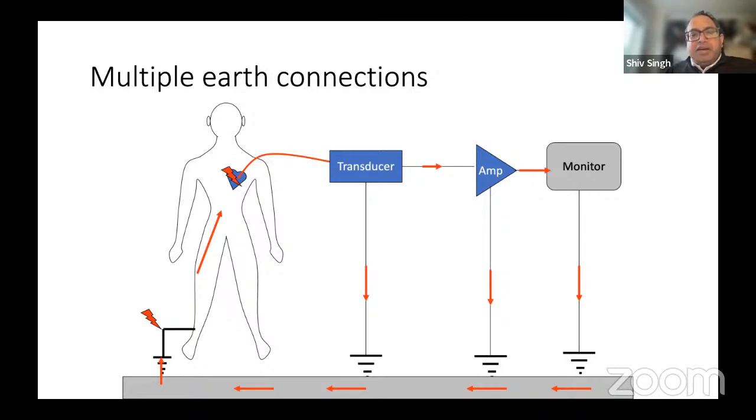And you say, oh, nothing has happened to the patient. Why is it that's happening? This could be because of the multiple earth connections. So it's very, very important in operation theaters that all the equipment that is connected to the patient is earth-free. Okay.